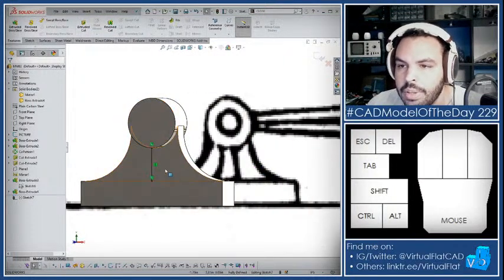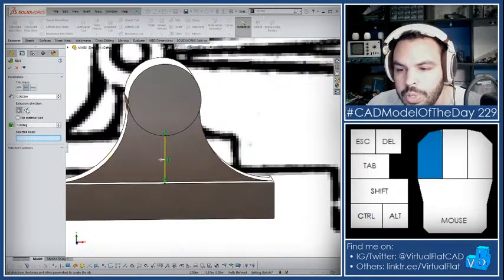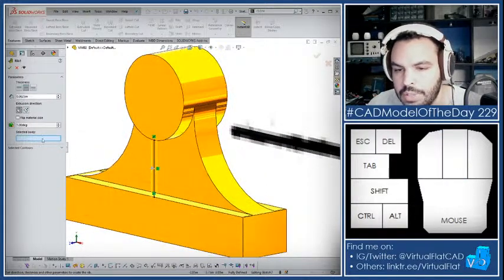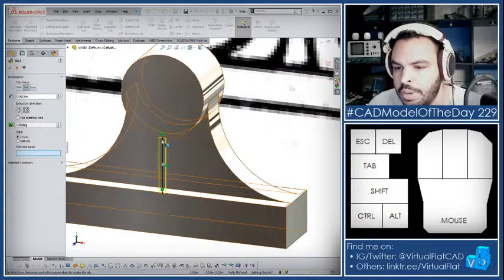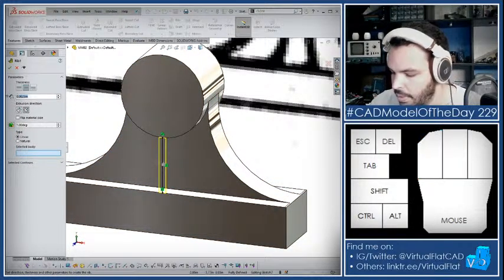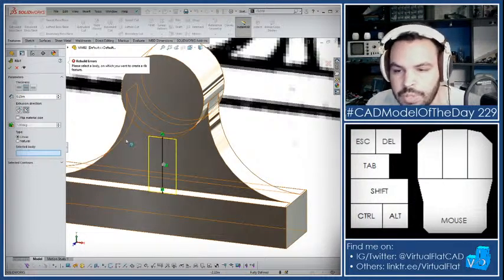All right, so I got a line here. Let's throw that to the rib tool. And rib is really cool because you can extrude in perpendicular directions. So originally I could actually go from side to side, but I can change it here, and now it's going inwards. 0.25 maybe. Oh, might have selected body.